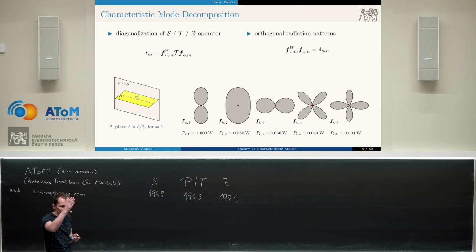And this is typically what we need from our basis, to have a compact representation, meaning that only quite a few modes can be used for that purpose. Okay. Together with the eigennumbers, whose meaning will be explained later, and together with characteristic radiation patterns, you also get characteristic currents. So those are the source currents sitting in the region of your structure, here on the rectangular plate of aspect ratio 2:1. And you can gather a lot of information from visual inspection of these currents as well.